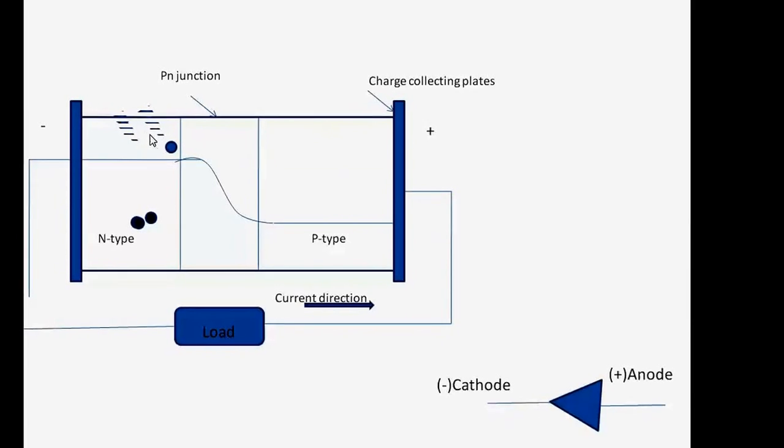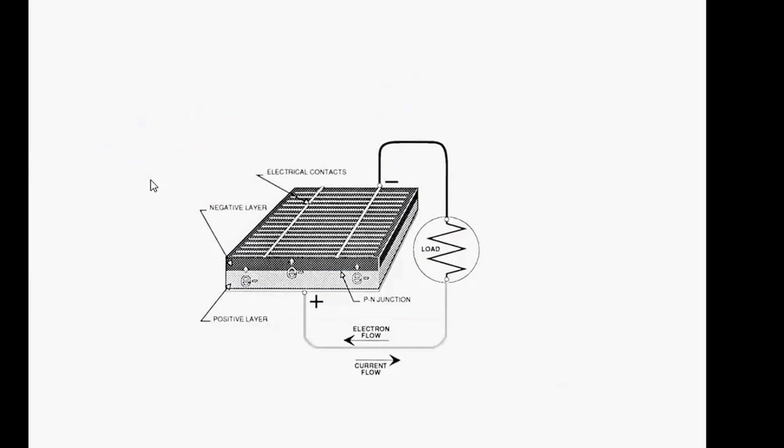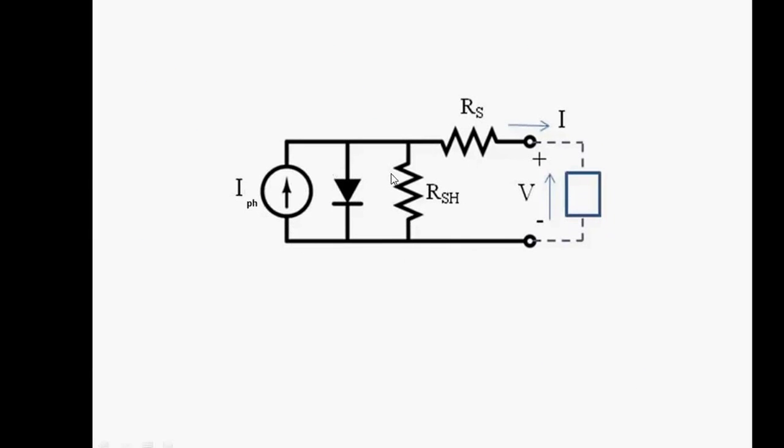And the shunt resistance RSH represents the conduction due to recombination, the recombination current. Actually, this is a kind of leakage process. So this path represents a leakage path for the photocurrent, and the rest of the current will be fed to the load.